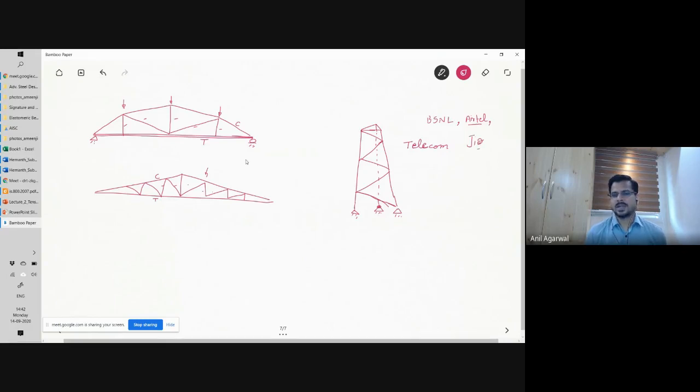Actually, I have worked on some telecom projects. That's why I know. This is not something you have to know as a structural engineer. Jio tends to use these triangular base towers, which are tubes. So the main legs are all tubes, and these are all angles. They have this kind of gusset plates on these tubes, and these tubes may sometimes have splicing, and tubular splicing is of a very different kind.